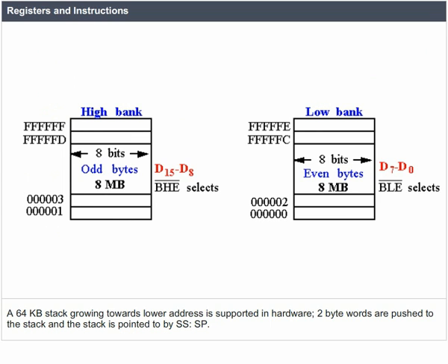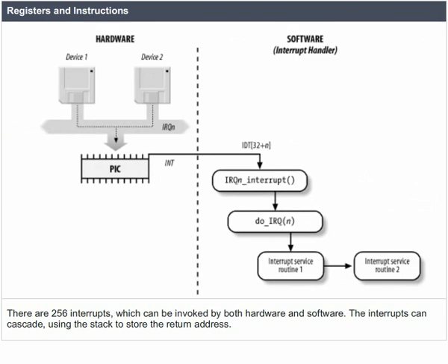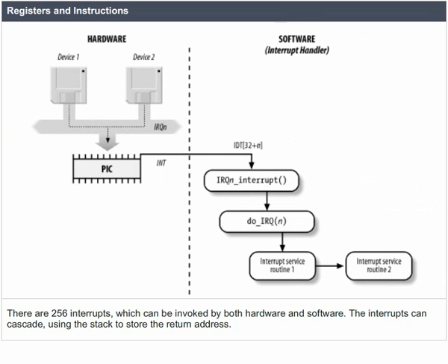2-byte words are pushed to the stack, and the stack is pointed to by SS:SP. There are 256 interrupts, which can be invoked by both hardware and software. The interrupts can cascade, using the stack to store the return address.